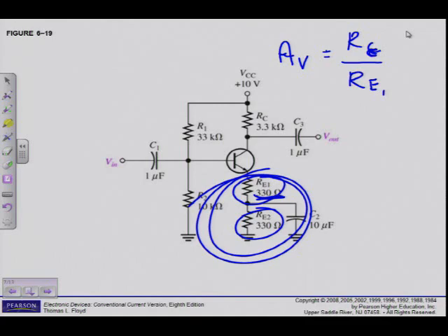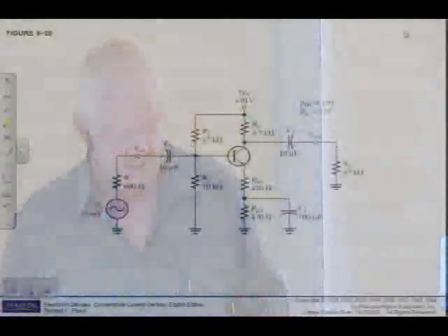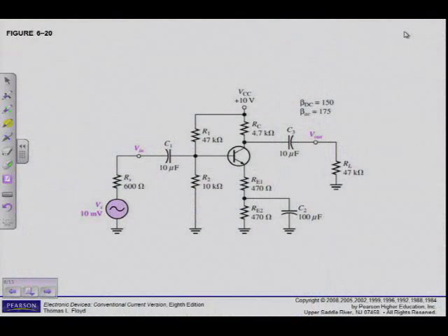Okay, then you can mark example 6.8 NB, NB, NB, because this brings the whole common emitter amplifier together. We can do revision quickly, but you must go and do it more thoroughly at home. So there's my circuit, the complete circuit. In example 6.8, I can see that I have a common emitter amplifier, because the input is applied at the base and the output is taken at the collector, so the emitter is on AC ground.